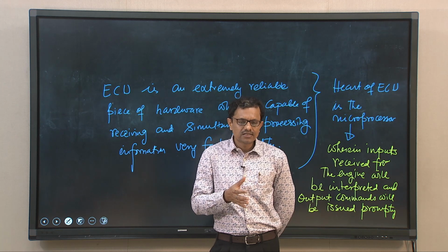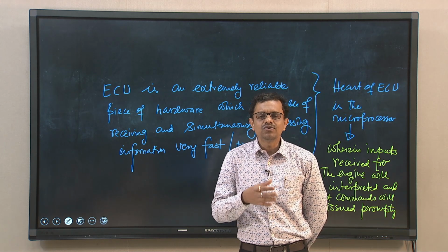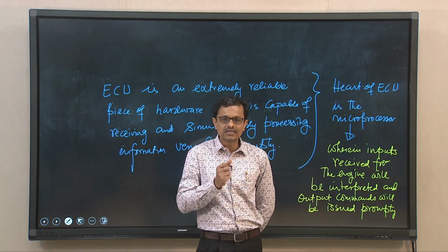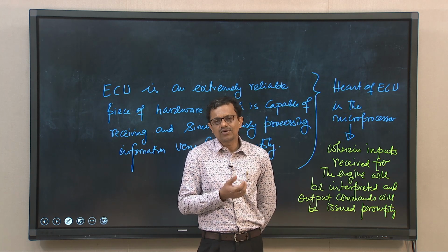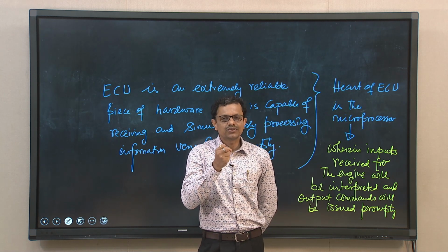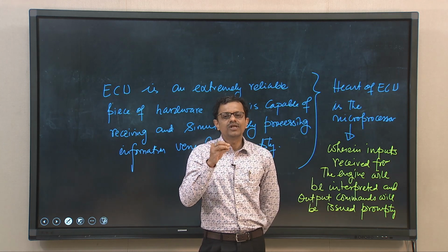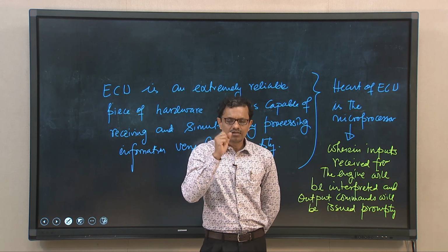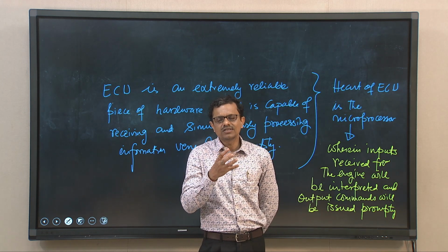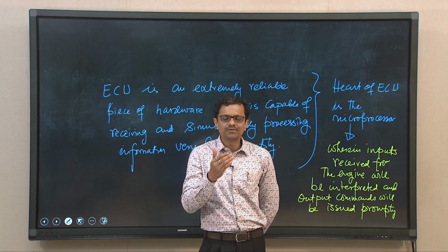so as to supply more air-fuel mixture by adjusting the throttle valve and other units of the carburetor. Another example I can give you: if it is a CI engine and, instead of supplying more air, we need to go for enrichment of fuel, keeping the mass flow rate of air intact, then certainly, taking input from the sensor at the fuel injector, that input signal will go to the ECU. And the speed control sensor will sense that the engine is now experiencing higher load, and that input will go to the ECU.